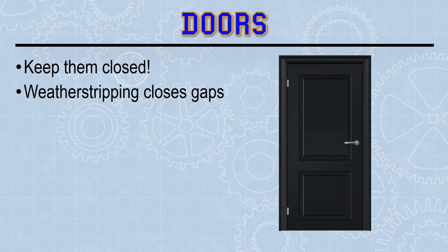Immediately after a building is completed, the doors fit snug in their respective spaces. Over time, however, the building expands and contracts slightly as it heats and cools with the seasons, and the doors may not fit as tightly anymore. Therefore, it's important to inspect these junctions annually and fill any gaps with weather-tight caulking.